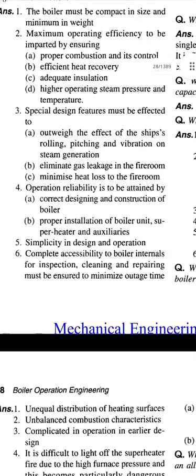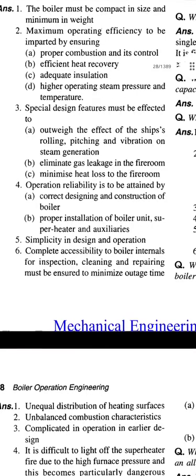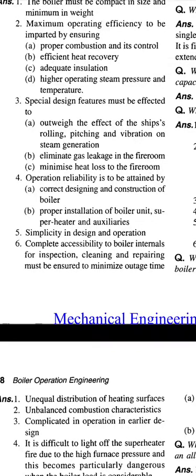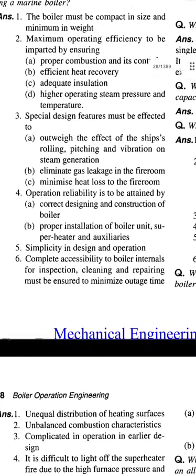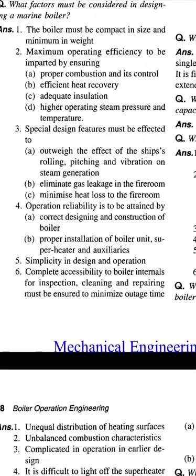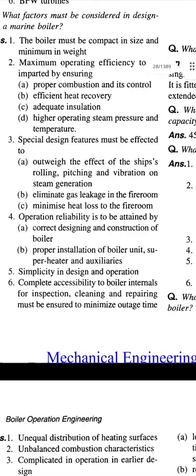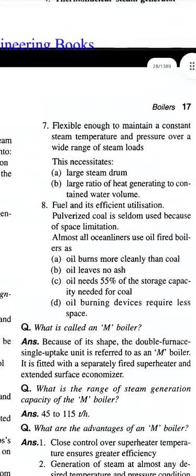Fourth one is operation reliability, to be attained by correct designing and construction of the boiler, proper installation of the boiler unit, superheater and auxiliaries. Simplicity in design and operations, and complete accessibility to boiler internals for inspection, cleaning, and repairing must be ensured to minimize outage time.